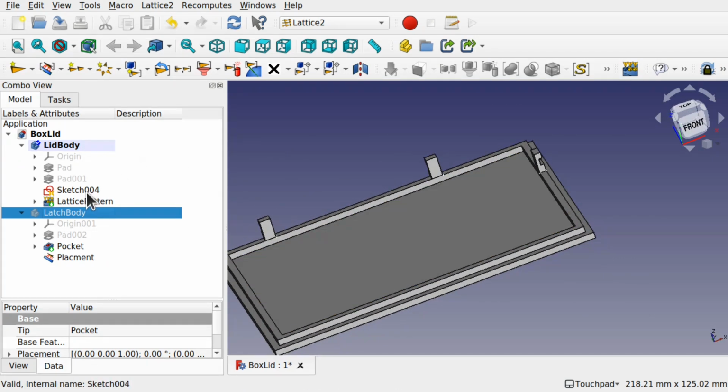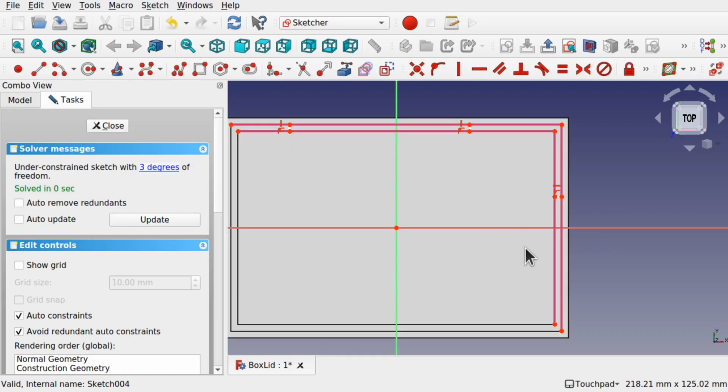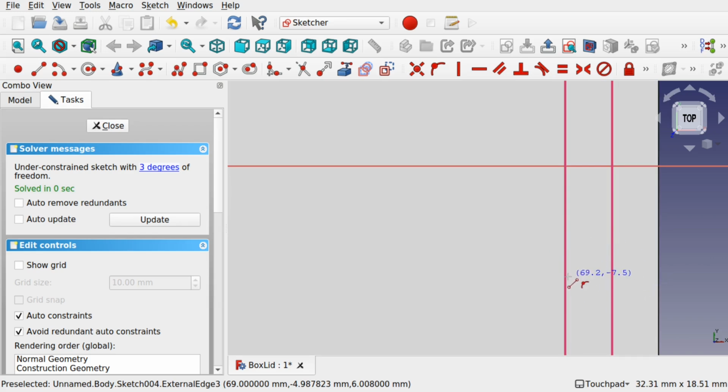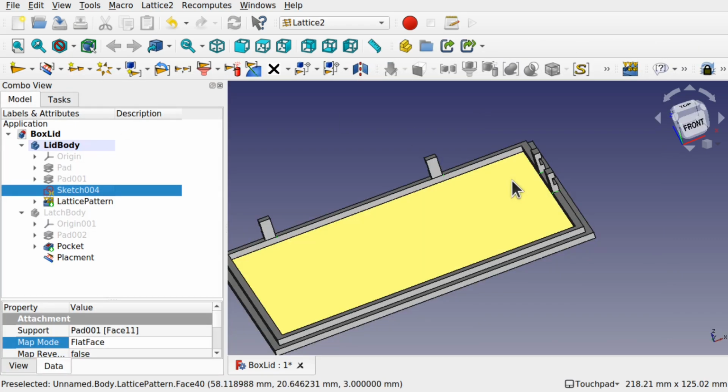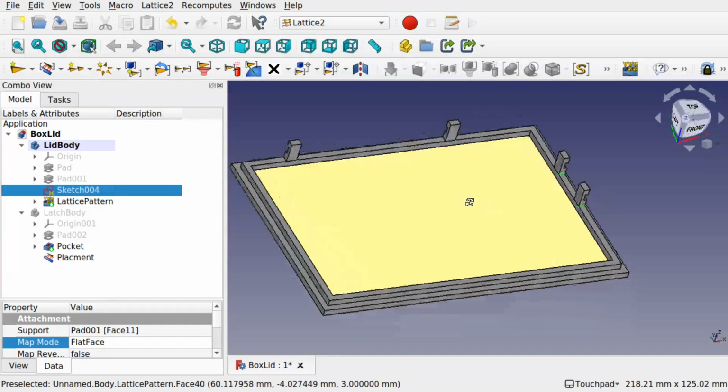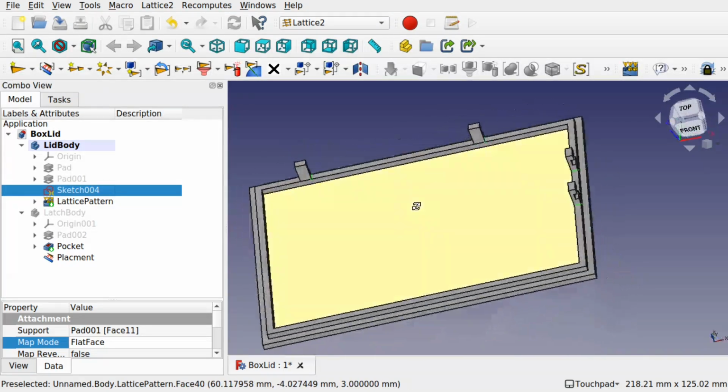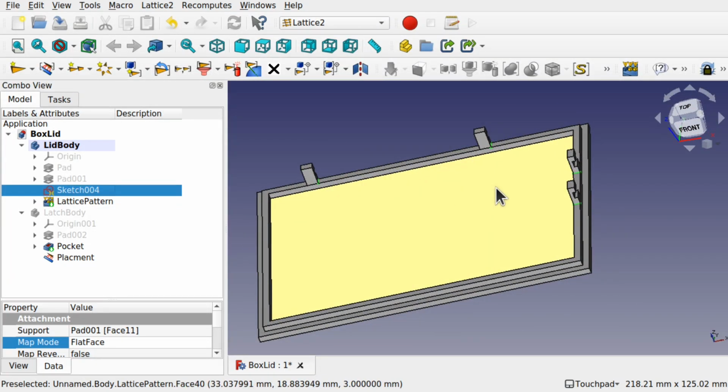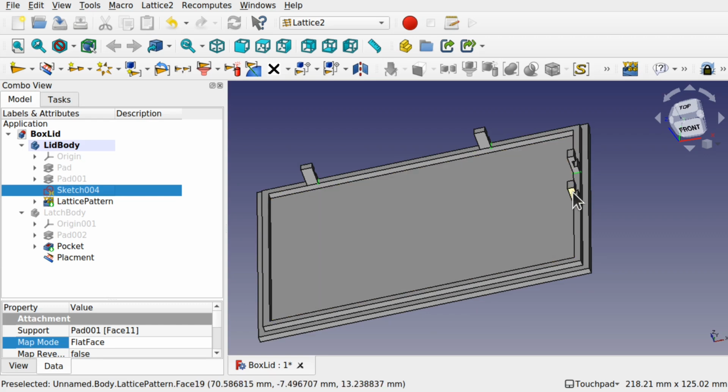Let's add another part to our sketch. So I want a placement using this line coming in, and I'm going to place it here and here. So what do you think will happen? Well, because we've placed it there, you just hit close, and we've got another one that's been attached. So we don't have to go through any other changes to our part. We just add these in.